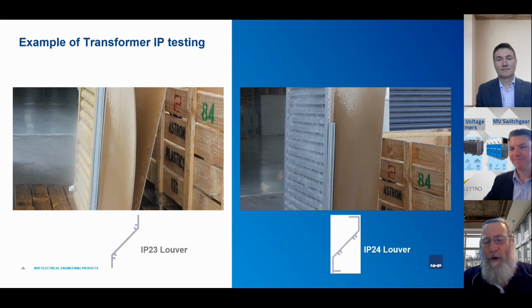The crazy thing is that at the end of getting the type test and everything approved, I subsequently found out that out of the 63 original transformers delivered to West Wind, it was only 3 or 4 of them that were right on the coast that had the water driving up horizontally and through the louvers into the oil containment.